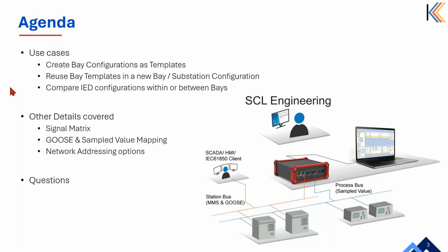In the previous versions of SCL Manager, we were focusing on the SLD as a template. That means you need to draw the single line diagram, and if you have a default way, you can save it as an SLD in SCL Manager, and you could replicate that SLD over and over again. But the IED was not included as part of that template in our earlier releases. So in the new release, what we are focusing on is to extend that bay configuration with IED configurations as well. That way you get a complete package.